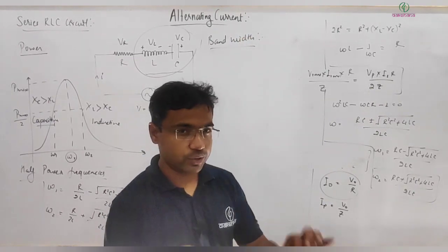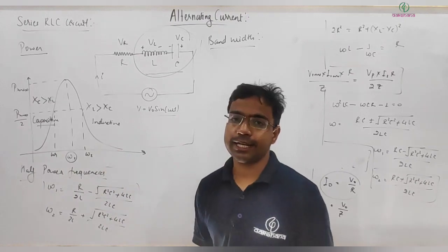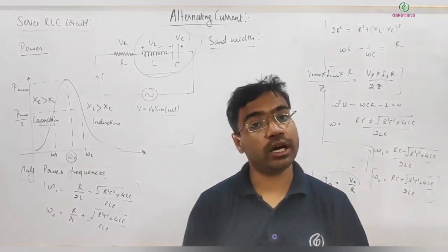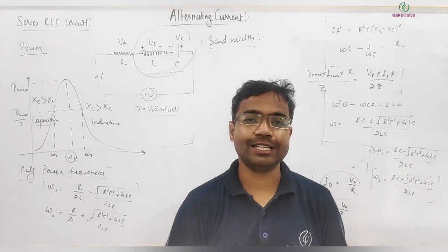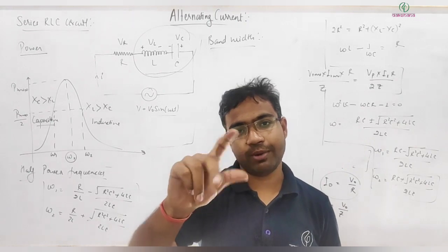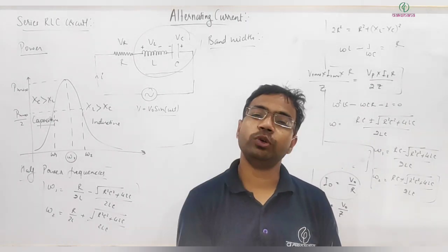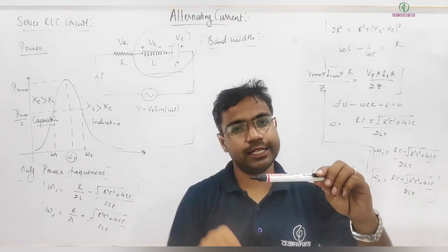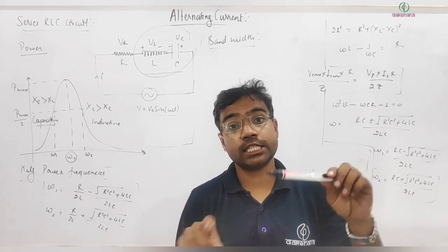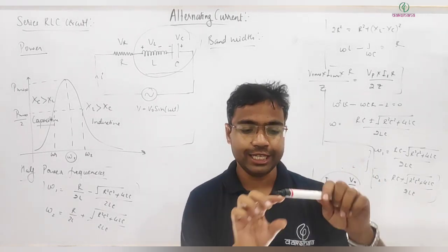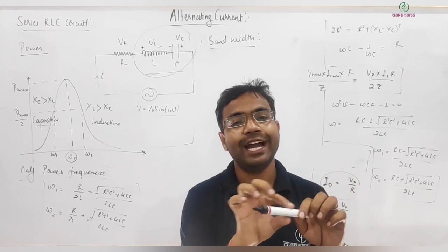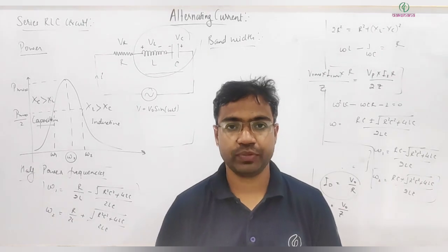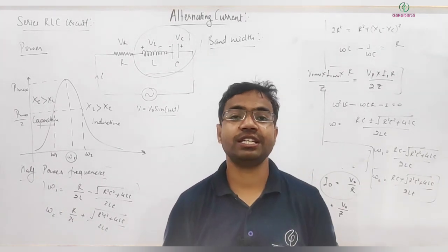Okay, now listen, let me tell you, so that will make sense to you. Actually, these circuits are used in our electronic instruments, telegraphy, and the radio you might have definitely seen before. Earlier we used to have one rotor sort of thing. If you open it, inside there is one wire connecting with some copper coil, and when you are changing the channel on your radio, this rotates. By this, in that circuit we are changing what? Frequency. Because the RLC circuit is there, so there we are changing the frequency.